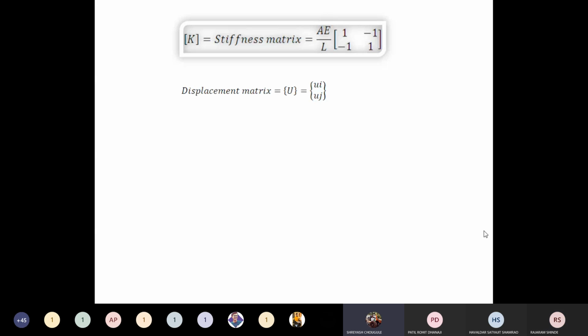Ability to resist. What is the unit of stiffness? Newton per millimeter. Sorry, yes, Newton per millimeter. Am I right? Now it is the force required for unit displacement. Stiffness is the force required for unit displacement. You have to remember this. And here, in the deformation equation, it is the force required for unit deformation.